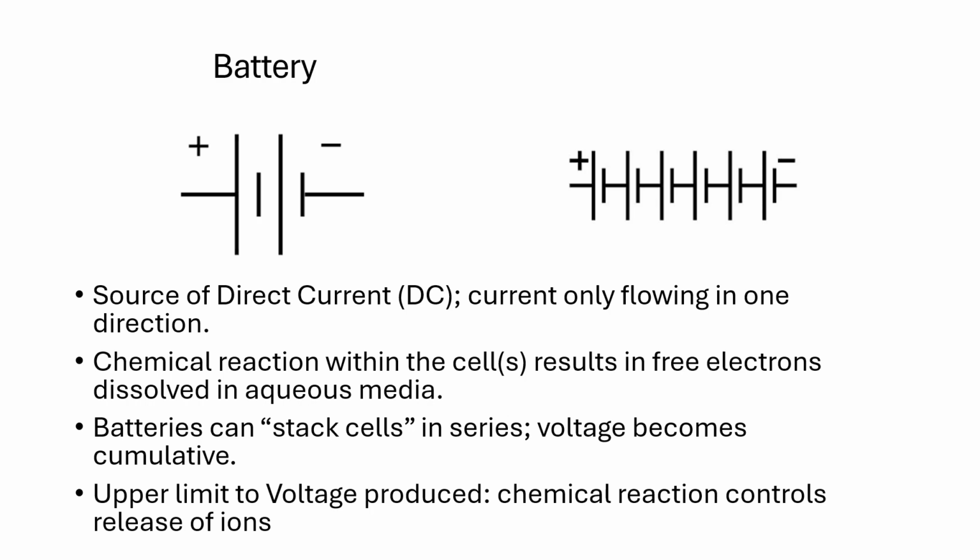And if you connect the batteries in series, the wires that connect the positive terminal of one battery to the negative terminal of the next are going to be pushing a whole lot of current because they're going to feel the push of all the batteries. And so you're not going to have wires thick enough, and you're going to create a fire. Okay.